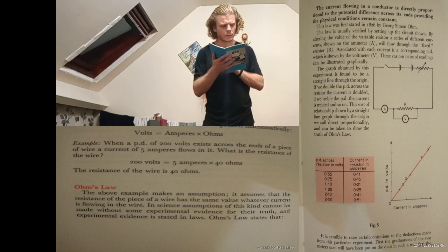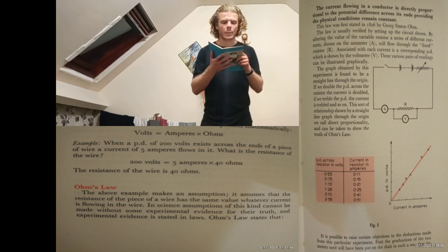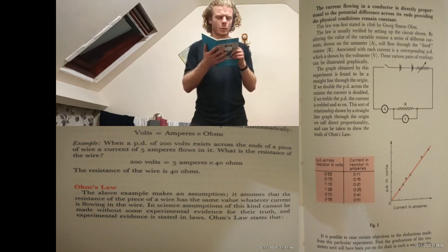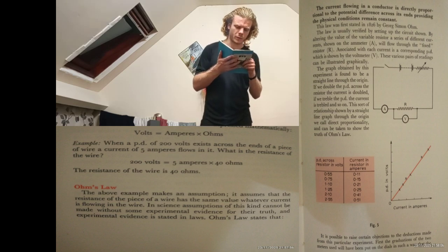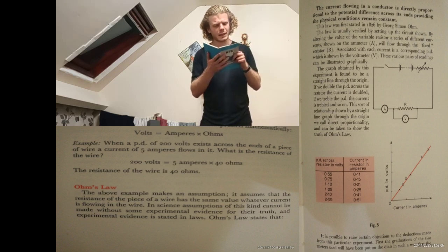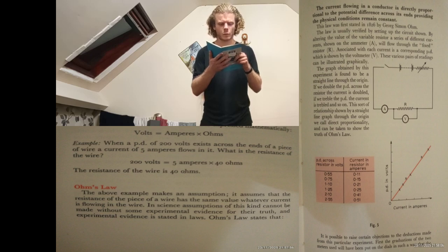Secondly, whenever a current flows through a resistor, heat is produced and the temperature of the resistor increases. We have to assume that the temperature rise is so small, indeed we use only small currents for this reason, as to have an insignificant effect on the values obtained from the two meters.